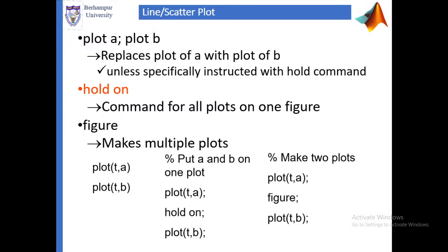Unless you have given a specific instruction to see both the plots, this will extinguish the first plot. What is the instruction for seeing both the plots? The instruction is hold on. The hold on instruction gives you all plots in one figure. Now on that you can have many figures. Figure is a command.